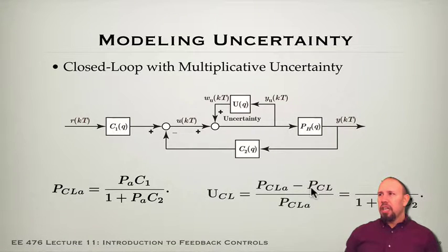And so we can see that the closed loop transfer function has a different uncertainty. And notice now the uncertainty of this system is a function of the controller, in particular of controller 2. So this has controller 1 and controller 2 here. So it's possible by appropriate choice of controller 2 to make this uncertainty small. So this is one of the reasons for feedback, that we can actually deal with things like uncertainty. The uncertainty still is there, but its impact can possibly be made small.